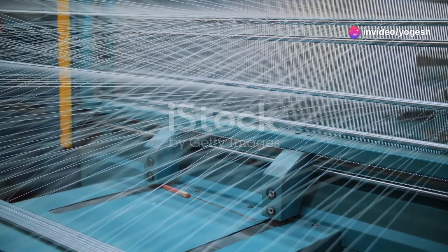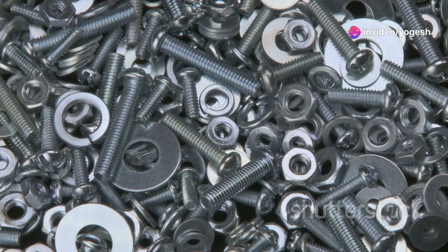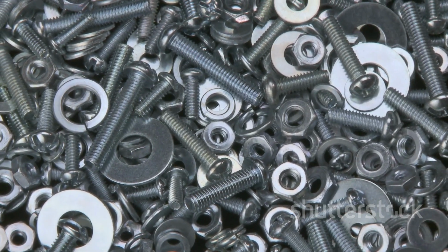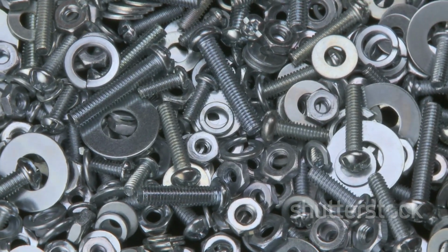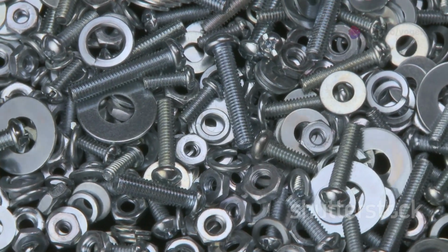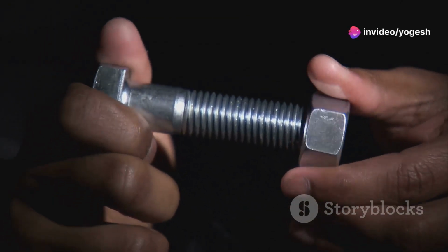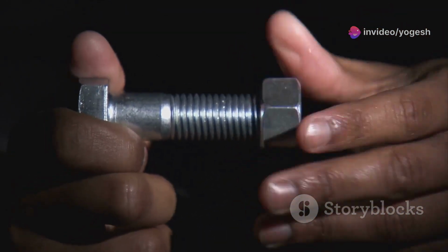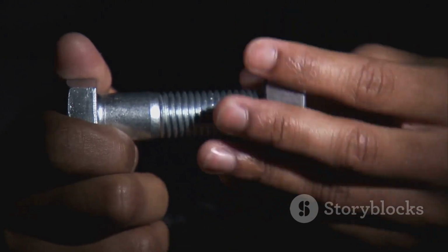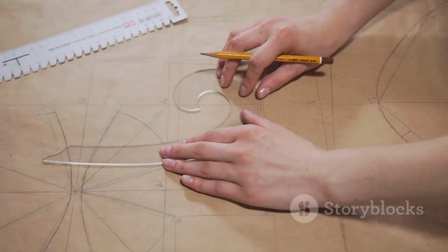Don't forget the chamfer. At the end of the threaded portion, add a small angled line to represent the chamfer, which helps to start the nut. The chamfer is a slight bevel at the end of the threads, making it easier to engage the nut and start the threading process smoothly. This small detail can make a big difference in the ease of assembly and the overall performance of the bolt.